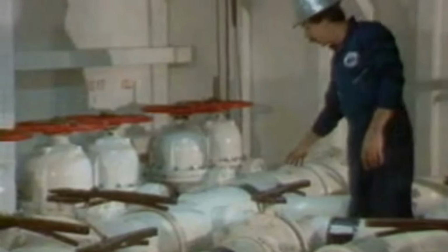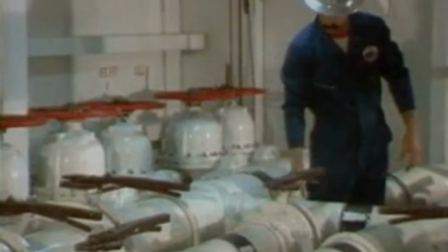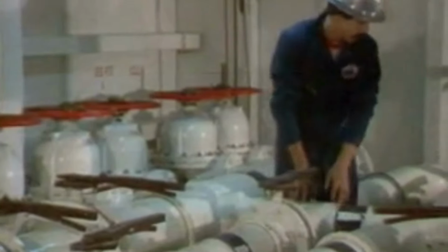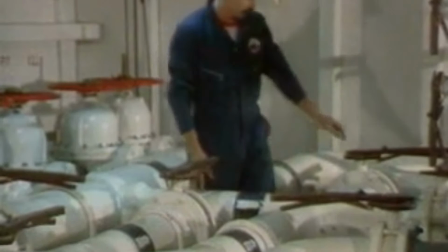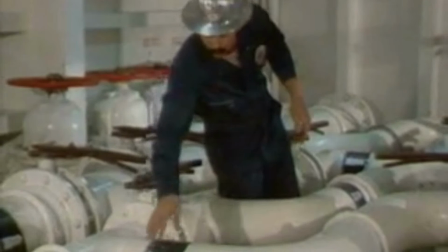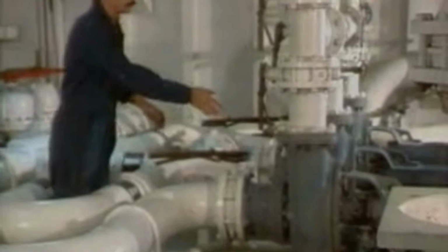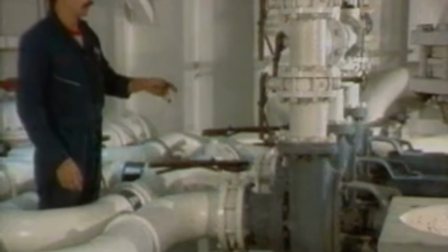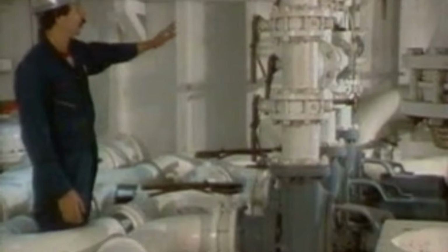The route it's going to be taking is coming through the line. It'll be coming through this smaller line. The mud will go right here and dead end because the valve is shut. It'll come back and it'll go through this route here. Continuing on, it'll go all the way through this line, around this L, back into the centrifugal pump. When I turn the pump on, it'll then be discharging through my discharge manifold, which is this entire system here.